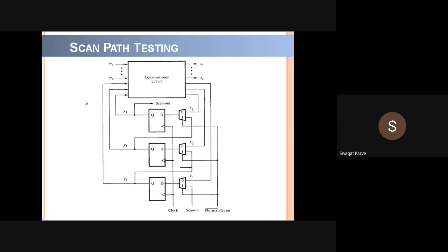So simply by connecting that JTAG wire to your computer or to that testing circuit, you can directly check the entire board, functionality of that entire board with the help of that JTAG port. And nowadays this facility is available, I guess even your ARM board has that JTAG port, right? So you might be aware of this.